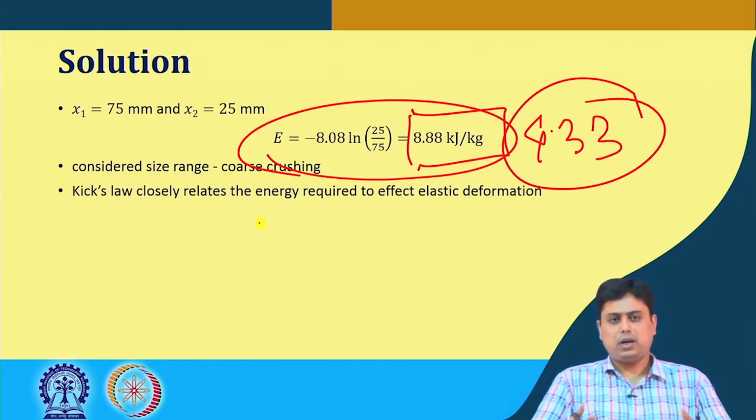Is it for the coarser particles? Is it for the finer particles? What is the ultimate result that you are producing? What is the desired product size, and from where is it happening? If you see there are chances of huge surface area creation, then the energy required would be more reliable from Rittinger's prediction.